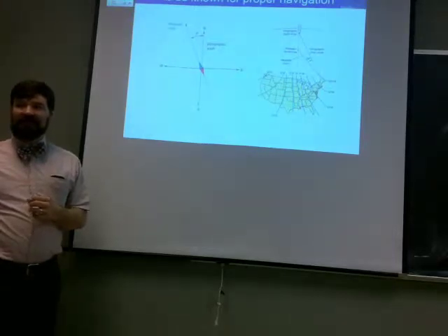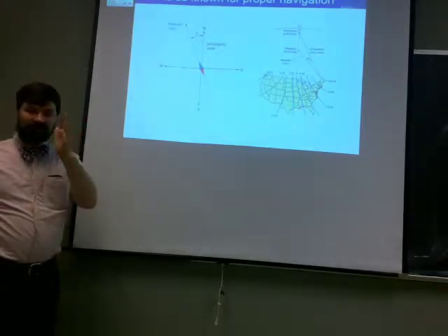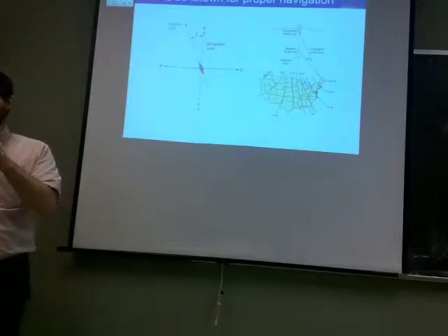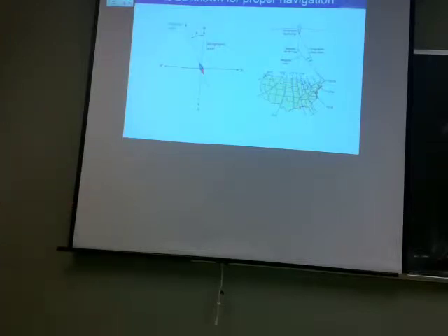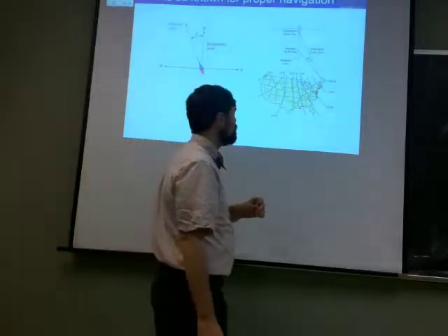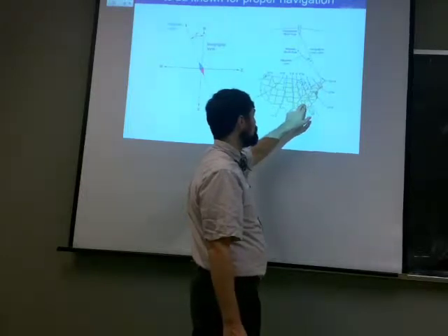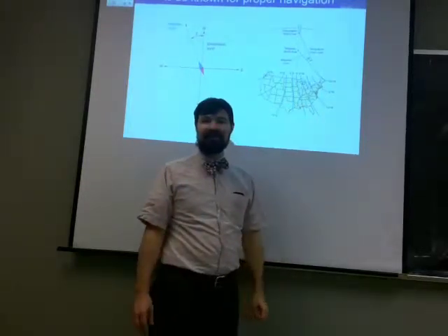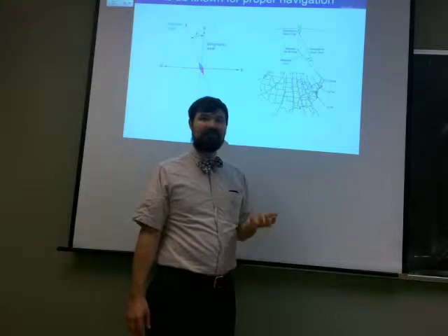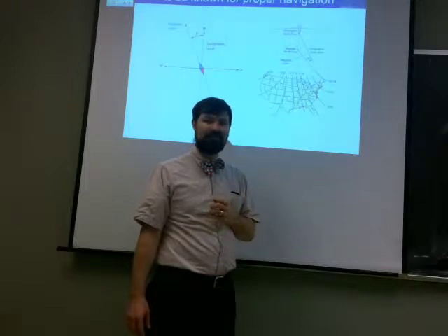It means you have an angle between actual magnetic north and what your compass says is magnetic north, which is about 20 degrees off. And if you look closely at this map, we're about here. We're pretty close to the 0 degree declination. So compasses are actually pretty good here. You might be off by like 1 or 2 degrees in Troy.